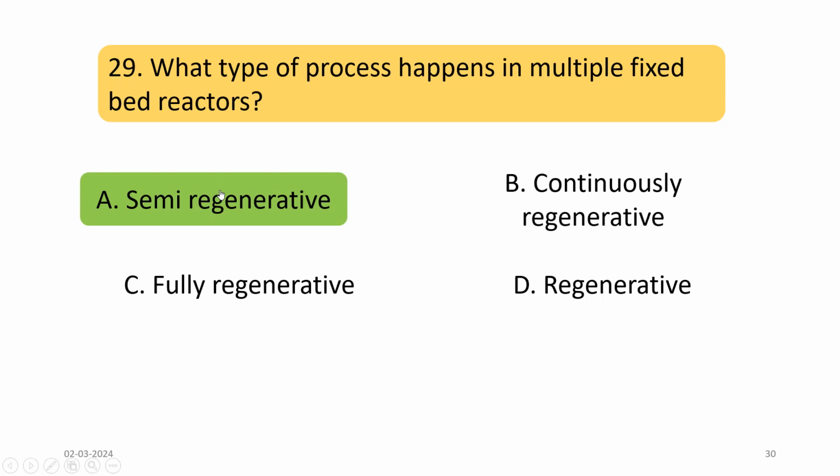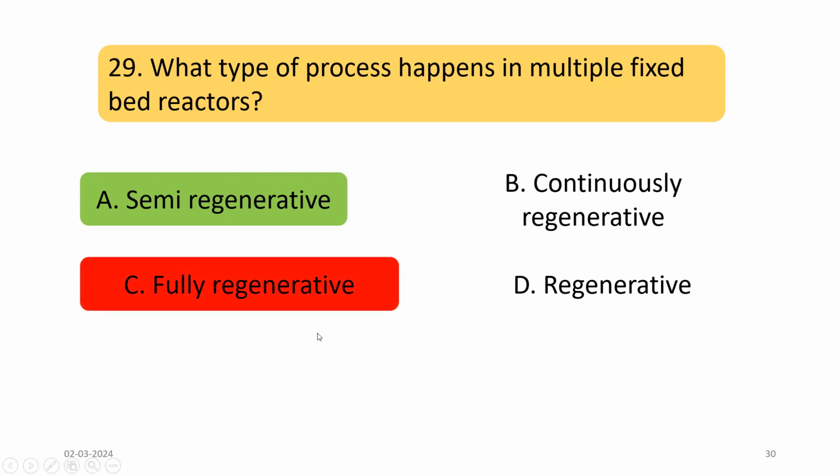The answer is semi-regenerative. Okay, not fully regenerative, because fully regenerative type of process happens in multiple fixed bed reactors with swing reactor. But I have only asked here for multiple fixed bed reactors, so it is semi-regenerative.